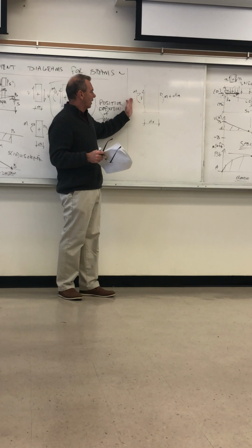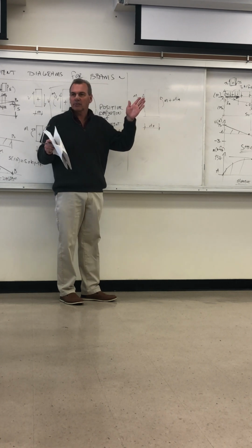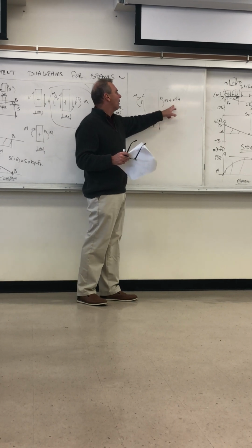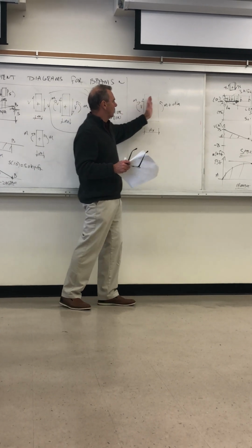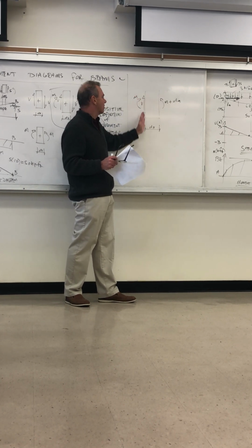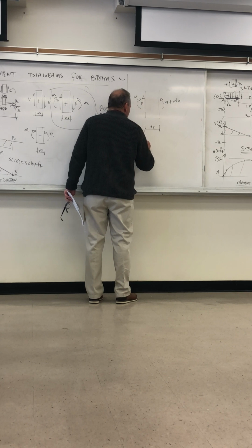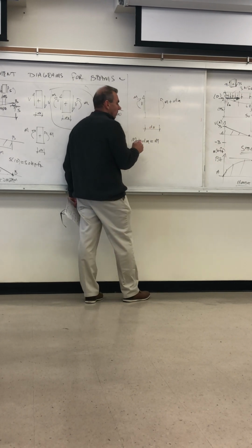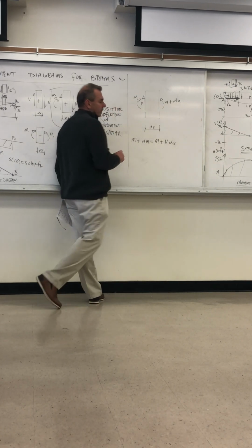We can say that we have a moment and a shear on the left of this segment that's cut across the whole height of this cross section. And then on the right, based on statics, even though this is a small amount, we can still write M plus dM. The reason is we have M here, and then over here, a differential distance over, there's the same moment based on statics, plus this shear times this distance. So we have M plus dM equals M, the moment on the left of that section, plus the shear force times dx.